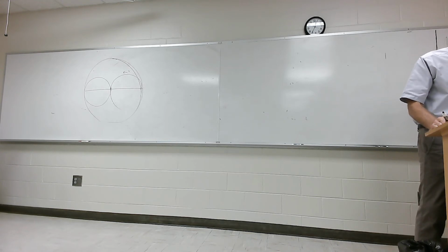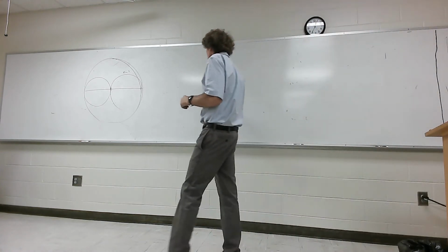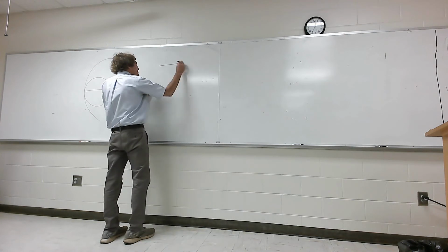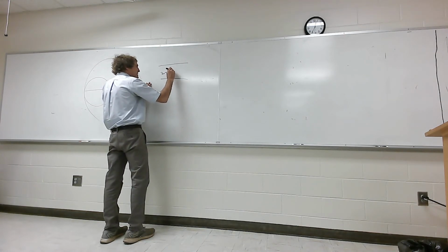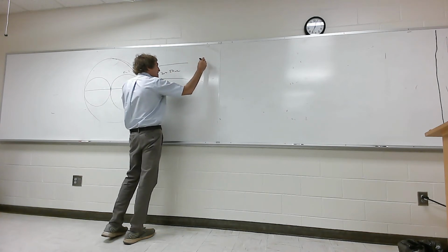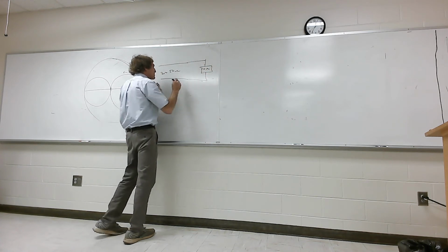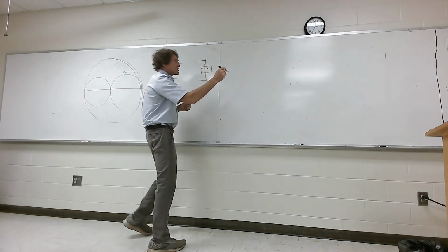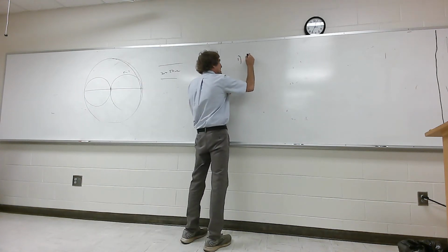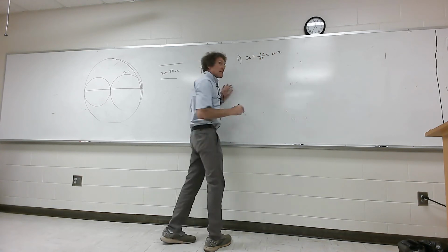Okay, so he says he's got a 10 ohm load to a 50 ohm line. This is an interesting one. He's got a characteristic impedance Z0 equal to 50 ohms, right? And then he's got a load of 10 ohms. This is kind of an odd one, there's no imaginary part to this. Do y'all follow me? We want to do a matching network. So our first step is to find ZL, that's 10 over 50, or 0.2, correct?